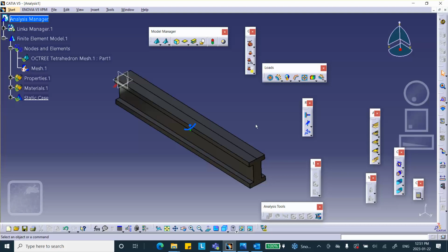That's what plane of symmetry means. You can't just cut the geometry. You have to make sure you put rollers or surface slider on that cut plane. But I'm not going to do that.